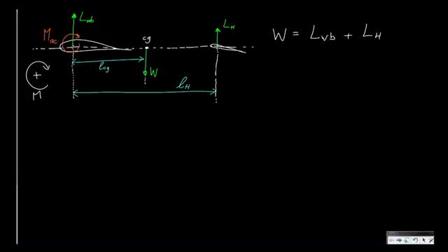And this is in total the lift of the complete aircraft. So if these conditions are met, then we have a vertical forces equilibrium. And this is normally done by changing the angle of attack of the wing so that this total equation holds and that we are keeping our altitude.